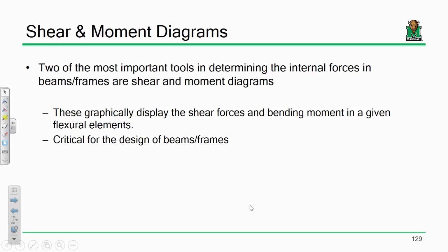They're pretty basic stuff. Well, another very fundamental basic skill for an engineer is having the ability to draw a shear and moment diagram. Anybody who graduates with an engineering degree, anytime, anywhere, knows this is a fundamental skill. The reason is that in order to properly design anything that's being bent, a beam, a frame, any element in any system that is experiencing bending or transverse shear, you need an understanding of the distribution of shears and moments across that element in order to design it.